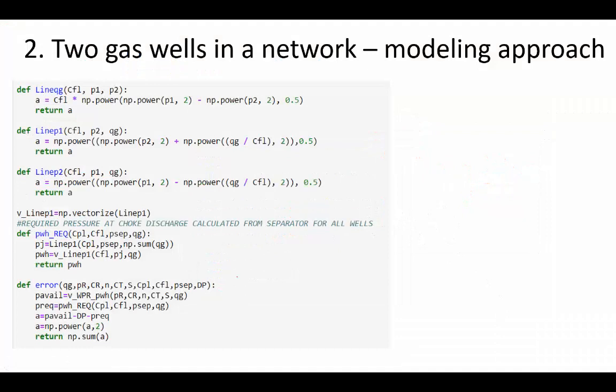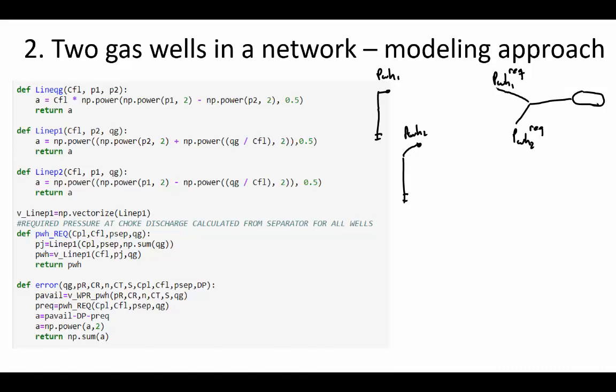Okay, so then I have, remember, my wells, that they go up to the choke, this wellhead pressure 1, and I have here also wellhead pressure 2. Then I have this system where I have my separator, then I have these two guys where I have the P, and unfortunately they are also called P wellhead pressure 2, but this is required, and P wellhead pressure 1 required, which is not wellhead pressure, but is essentially the pressure. Then I have here a choke, this choke element, where I have delta P choke 1, and here delta P choke 2.